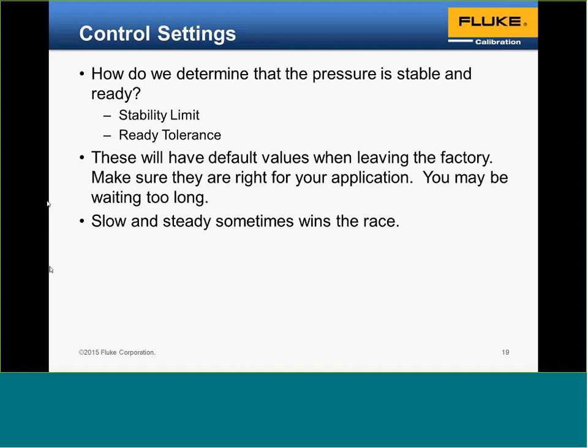The values when leaving the factory are many times very close to the overall best performance of the instrument, but you need to set them for your application. Maybe you don't require as stable a pressure for your calibration. Otherwise you're waiting too long, waiting for something to stabilize when you don't need to.